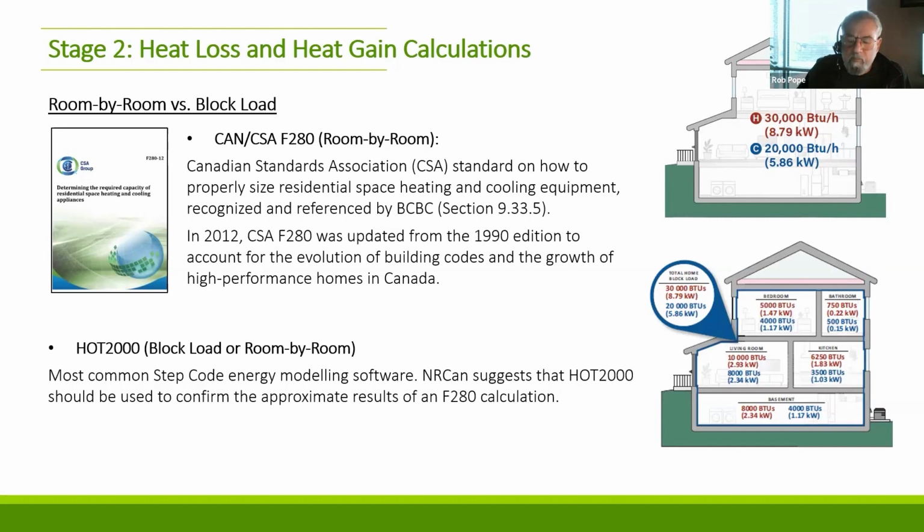Another load calculation methodology, but is not CSA F280, and it has a different purpose and is often confused with CSA F280, is HOT2000. HOT2000 is what the energy advisors use to determine the performance attributes of the home, the energy performance attributes. It's an energy modeling program. It's what it's intended to do. Enercan, that created the program, doesn't like you to use it as a design tool. They want you to use it just as an energy modeling tool only.